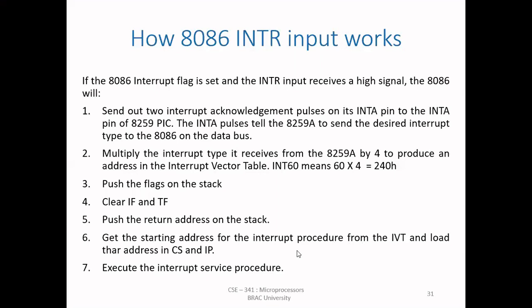So this is how an INTR input works, but you have to remember that at first it will send two interrupt acknowledgement pulses through its INTA pin, two pulses.